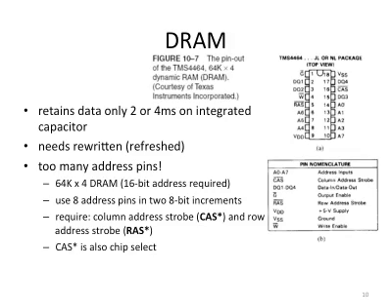The next type we're going to look at is the dynamic RAM. Dynamic RAM supports both read and write, but because of the design, it's different from SRAM, where we use 6 transistors to store a bit. In DRAM, we just use 1 transistor to store a bit. Because of this property, the DRAM has a unique feature.